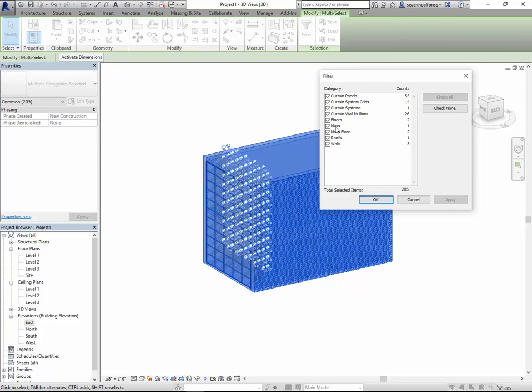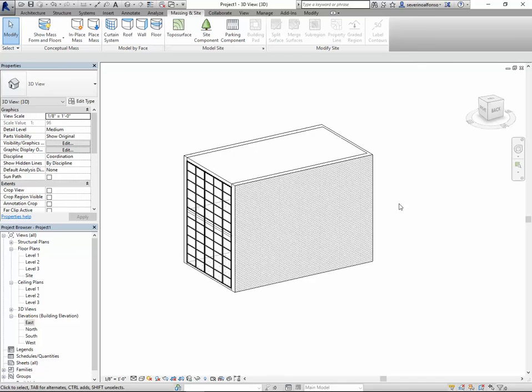We needed them to create the floors and the walls, and we created the mass floors from the massing options. So in that sense, we don't need the masses and the mass floors anymore, but they're there. We have to be careful that if you want to start taking this out to InDesign, you always have to check here and make sure that the massings and mass floors are turned off.